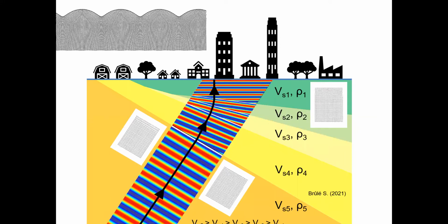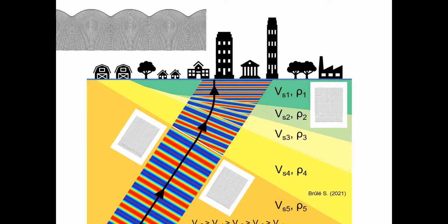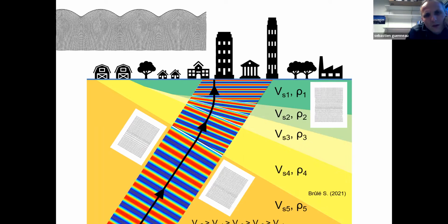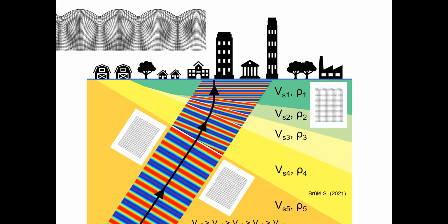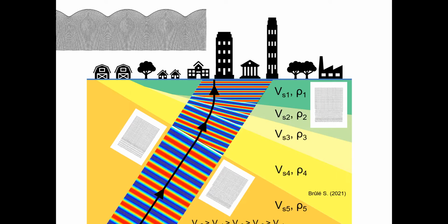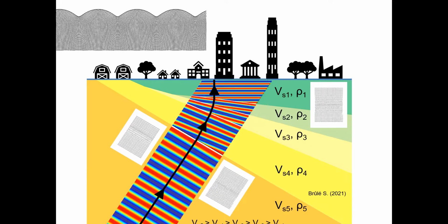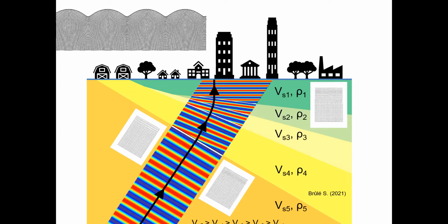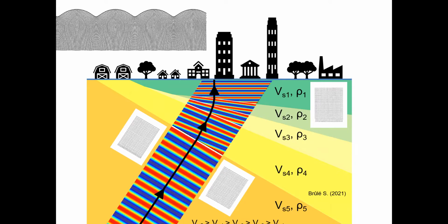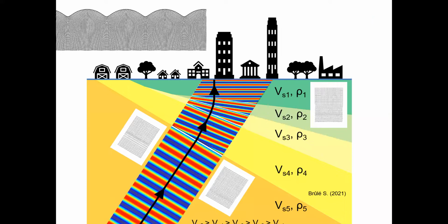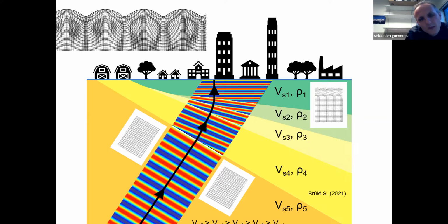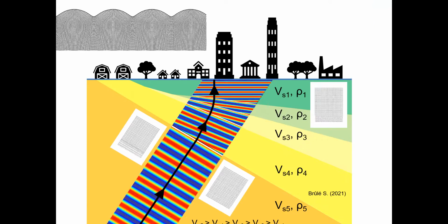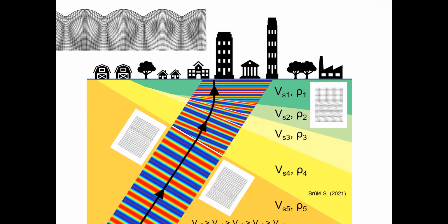You have to leave a space between the two buildings. This permits avoiding a shocking effect, because two buildings are not necessarily in phase. There's a phase shift between them. So if they are out of phase, they can shock each other. So you mean they are in anti-phase and they would collapse on one another? Yes, a tall one on a small one.